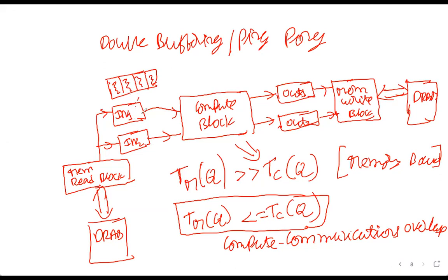Similarly for in1, in2, out1 and out2: when you are generating 1000 outputs, and if your output buffer has only one write port, then it will be trouble. So you need to split the output buffers into multiple blocks so that we can do parallel writes.